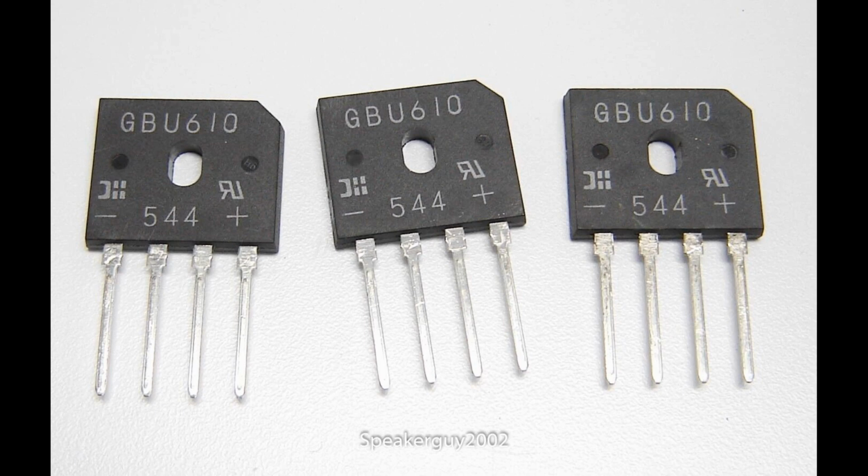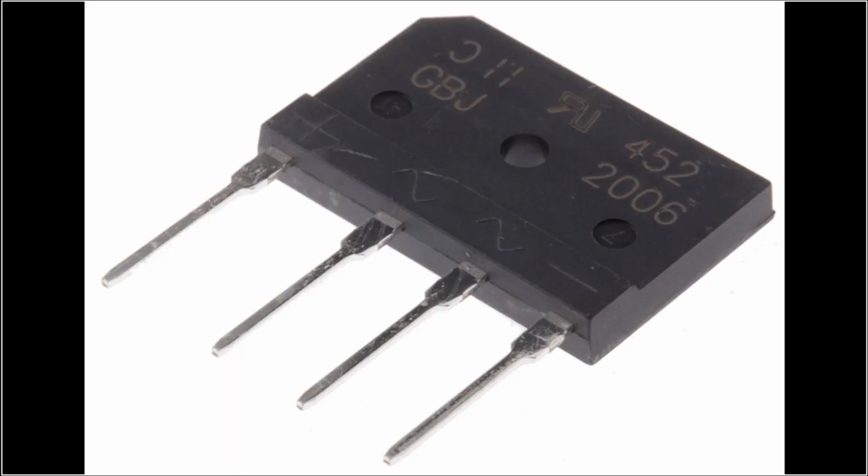AC to DC conversion. The main function of a bridge rectifier in a power supply circuit is to convert alternating current, AC, from the mains power source into direct current, DC. The bridge rectifier accomplishes this by rectifying the negative half cycles of the AC waveform to produce a unidirectional DC output. Full wave rectification. Bridge rectifiers provide full wave rectification, meaning they rectify both the positive and negative half cycles